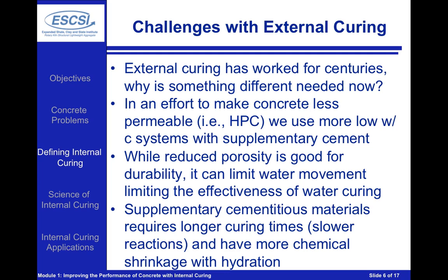The second reason why we're starting to see a big increase in discussion of the potential for internal curing is because as we move to using more and more supplementary materials, these materials are going to require a longer curing time because they're less reactive than our conventional cements. This means that we're going to need to keep water in that system for a longer time, and instead of ponding the systems for 2 weeks, 3 weeks, or 4 weeks, maybe we can supply that water in a different way. In addition, a lot of these supplementary materials have more chemical shrinkage than a classic Portland cement, and this is another reason why we would want to supply additional curing water.